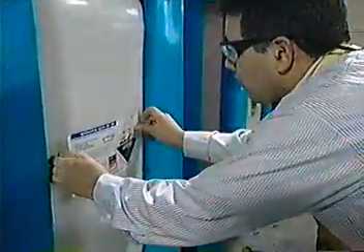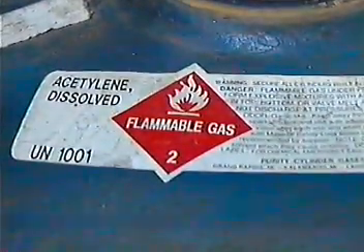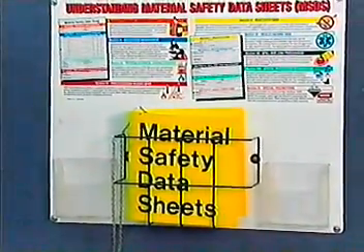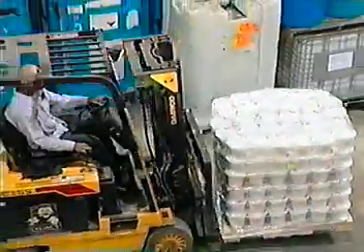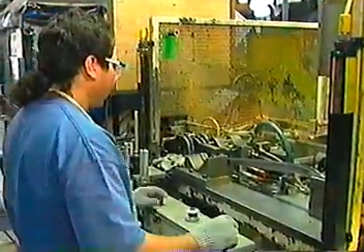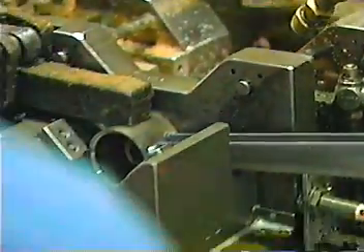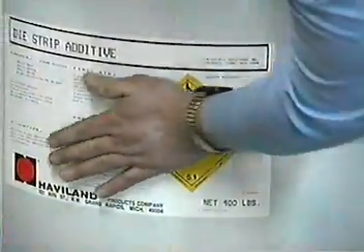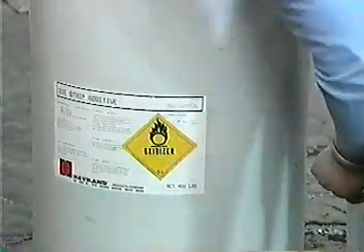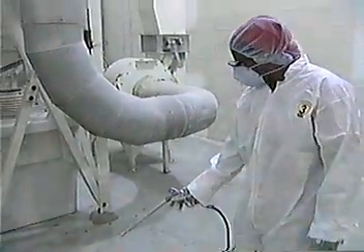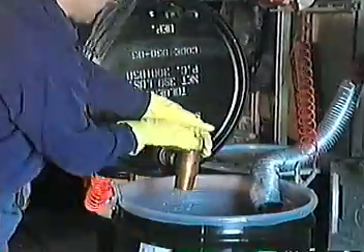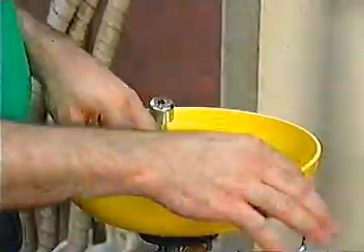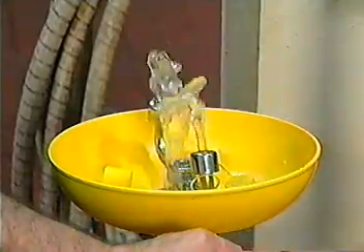Hazard communication gives you the information needed to handle potentially hazardous chemicals safely. It is important to understand how to interpret container labels and the information provided on material safety data sheets for the chemicals you work with. Before using any hazardous chemical, you should use these resources to understand important information about these chemicals, such as the health effects and physical hazards associated with handling chemicals, personal protective equipment to use while handling a chemical, symptoms of exposure to hazardous chemicals, and first aid procedures to follow in the event of exposure.